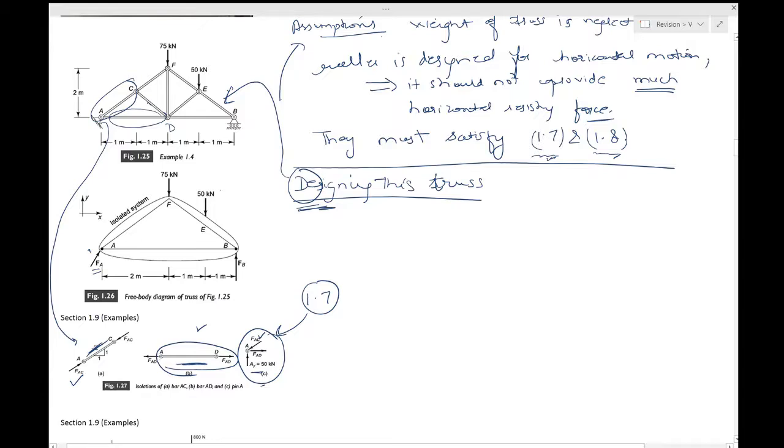Okay, so you will see that AC is actually in compression, AD is in tension, so one of them is being pulled, the other is being pushed, and then as a designer you can see, well, this material has to take up a force of say 70 kilonewtons, so what should be the material I should use? Okay, what should be the specific alloy which I should be using? Because every material is not the same, and so on.